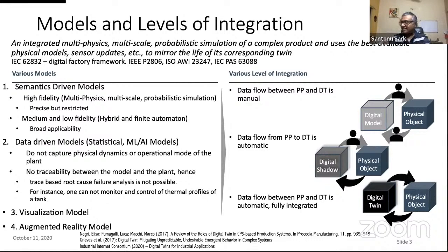If you want to really model the entire plant having, let's say, 10 motors and 60 valves, and you want to monitor each and every valve's condition, even though the valves are all similar, even though the motors are similar, even though the PID controllers are similar, you may require those instances because you may want to check the health of each of them. The same algorithm might be running, say the algorithm to detect anomalies in a motor. That is the same, but one motor might have different parameters compared to others. So those 3 algorithms would run in parallel and they would get different data.